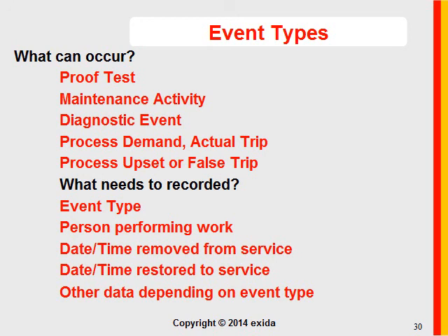You want to record that your layer of protection was successful. Or if that layer of protection failed and there's an operator that is supposed to take action, you want to record that that operator was successful or failed. And if that operator failed, that your safety instrumented function was successful or not. And if that safety instrumented function failed, that your pressure relief valve was successful.